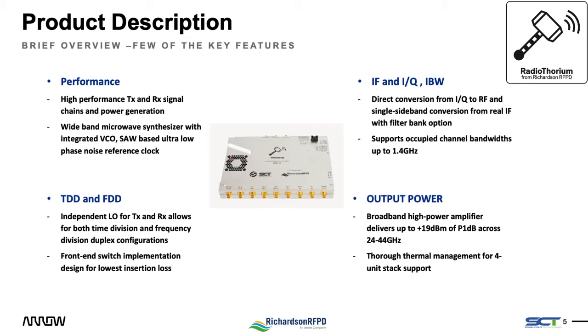This will definitely be sufficient to drive higher element count antenna arrays up to 256 elements, where multiple layers of splitting and combining are required to feed the multi-channel beamforming ICs. Those power levels will also be sufficient to drive higher power amplifier MMICs for applications like SATCOM and EW.